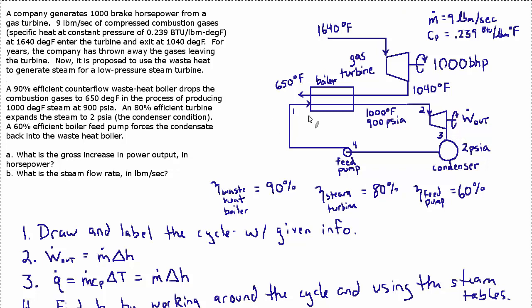On the other hand, when you're operating this boiler, you want to come in at as low a temperature as possible, or as low an enthalpy as possible, I should say, so that you can do as much heating as possible to reach the hottest possible condition at state 2. So what ultimately happens is that the pump increases the enthalpy more than you would want it to, so that the boiler can't do as much heating as you would like.